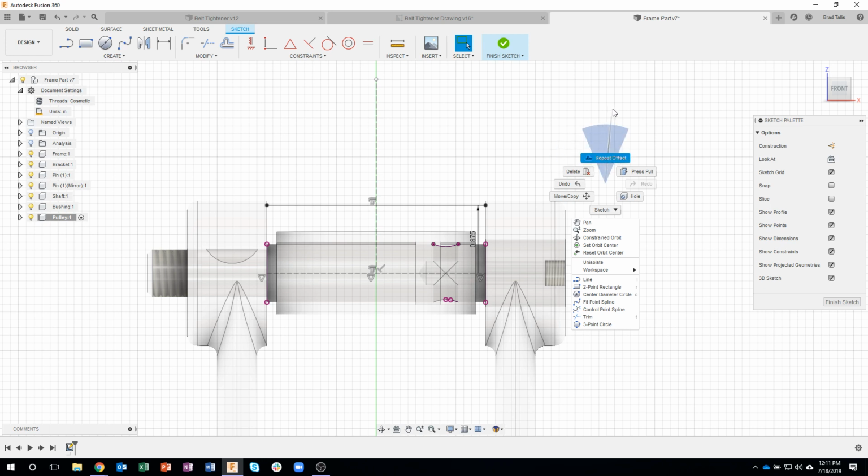But you'll notice this black line that's kind of stretched out from there. This is, again, called the marking menu, and the black line is what we call a gesture. So all I have to do, you'll notice if I go to the left, it's an undo. If I go to about 2 o'clock, it's press pull.